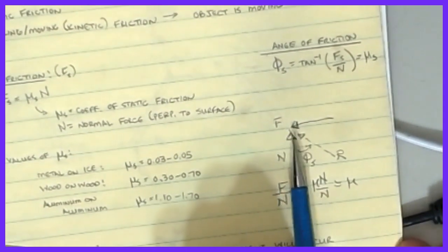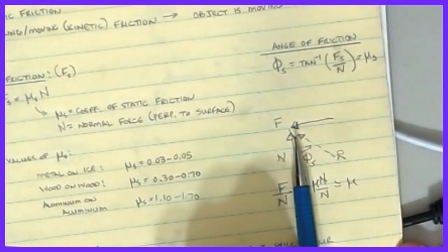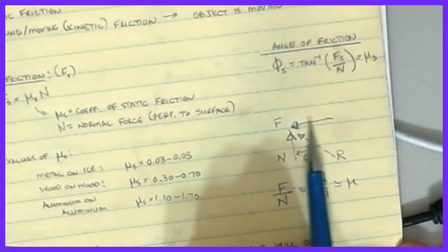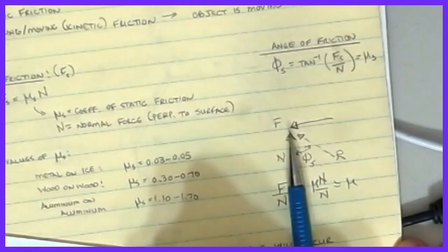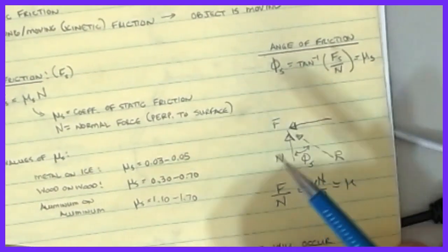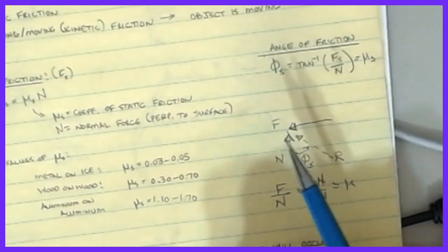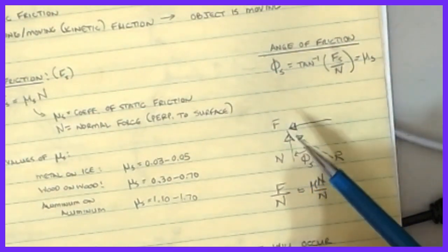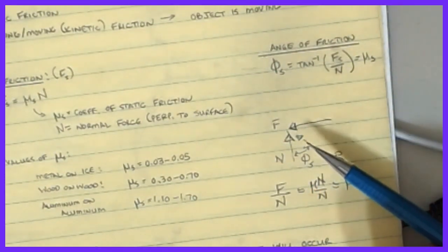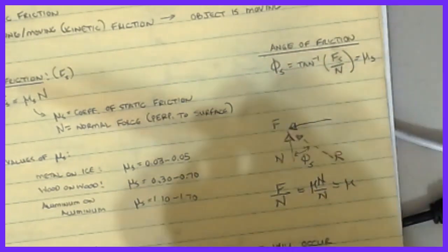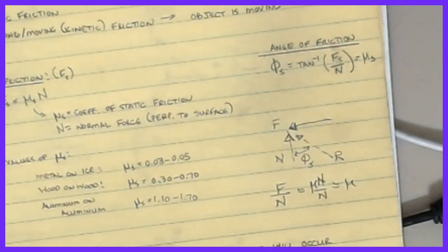But as you start to increase the force, that P force on your object, and you start to develop this P because the object is wanting to move, what happens is that F couples with the N and starts to incline the R, and eventually the R keeps moving a little bit further, until it reaches some limit, at which point it breaks free and is able to start to slide. Okay, and so that's one of the other logic checks that we'll start to look at.